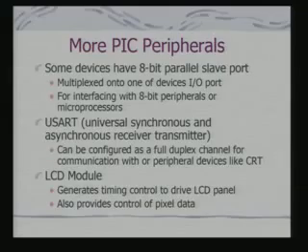There are other PIC peripherals, beyond what we have discussed so far. One is the 8-bit parallel slave port. Now, if you look at your digital I/O pins or the ports that we have discussed, what is the difference with them? The difference is, we have used them as single bit I/O ports. I can set individual bits to be either in input or output mode separately, and I can read them.